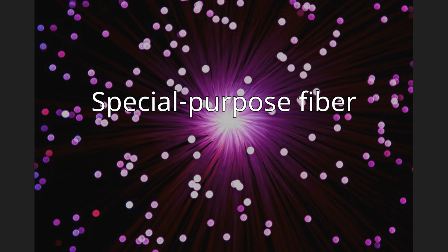Photonic crystal fiber is made with a regular pattern of index variation, often in the form of cylindrical holes that run along the length of the fiber. Such fiber uses diffraction effects instead of or in addition to total internal reflection to confine light to the fiber's core. The properties of the fiber can be tailored to a wide variety of applications.